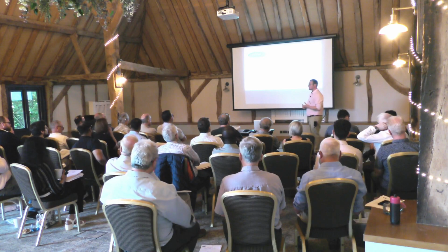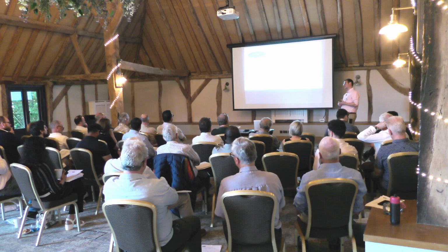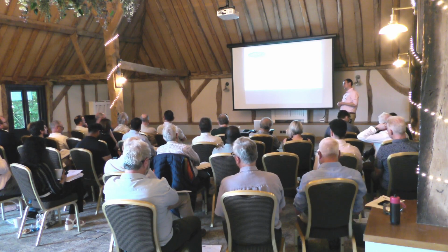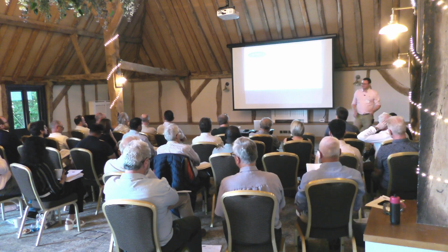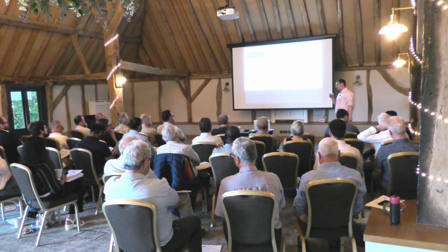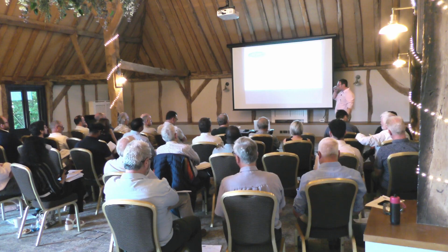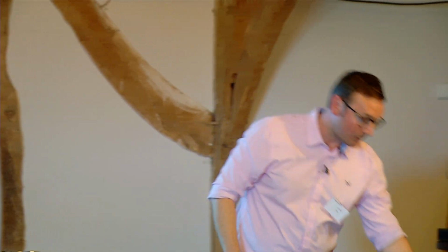Any questions? That's a good question. Yeah, of course. I had one recently when I did a downstairs extension, which was kitchen, utility and toilet. So kitchen, then door into utility, door into the toilet, inner room. Yeah, the local authority didn't like that. There are no windows in either the utility or the toilet. Sanitary facilities, bathroom, WC or shower room is permitted. Utility room is fine. So 2.11 says. They wouldn't back down. I'd point them towards 2.11.